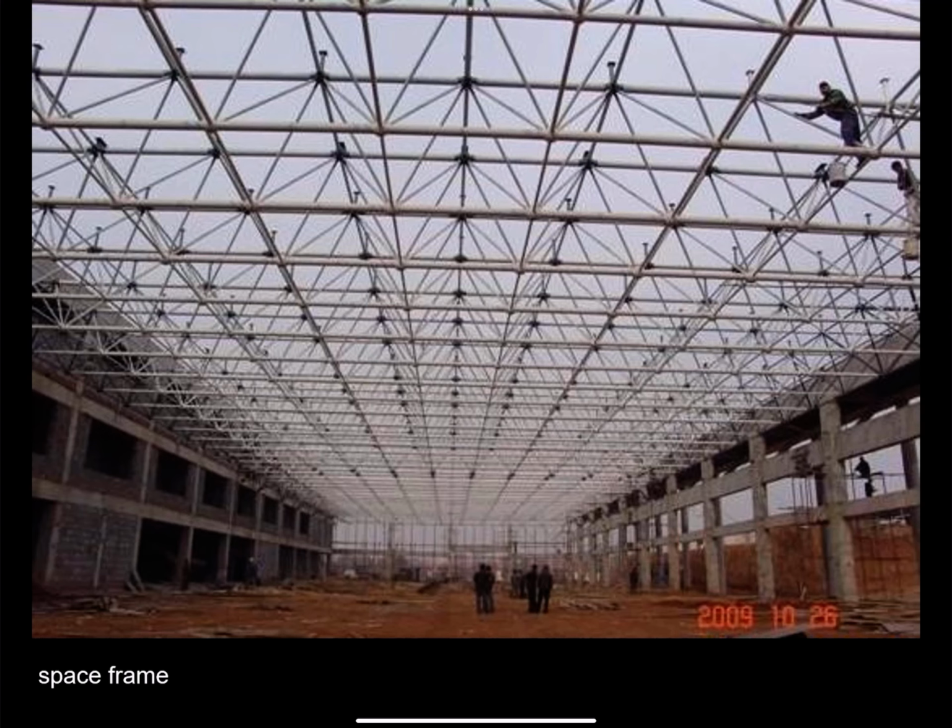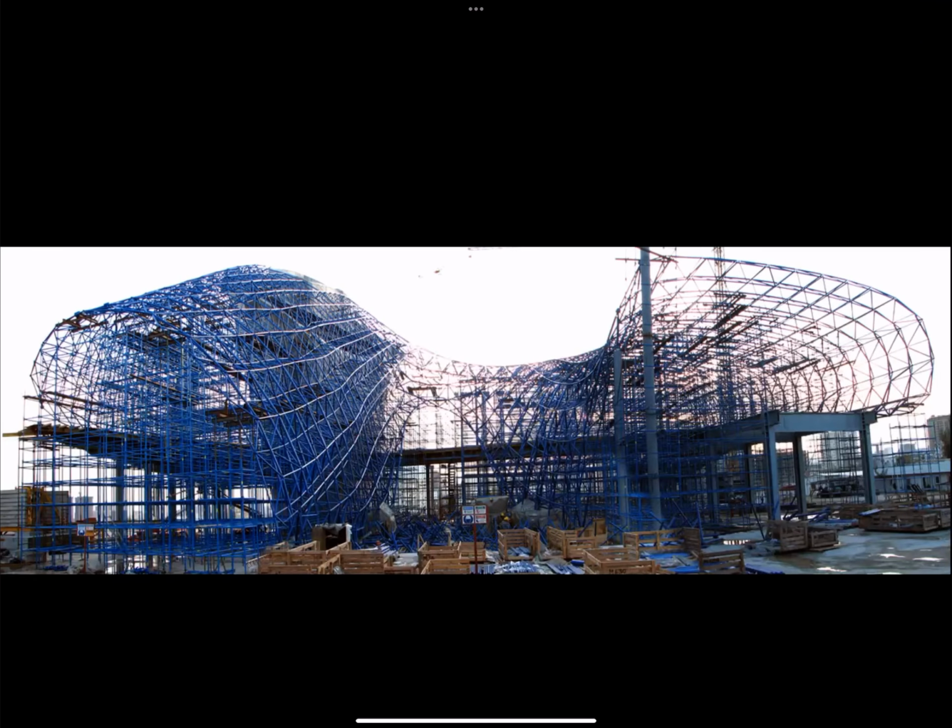And so the depth of this plane is probably about 8 feet. You can see that the worker can stand in the depth of the structure. You can see that the structural elements are very slender. And this forms an extremely stiff structure that can span up to 150 feet. And so this is called a space frame, the continuously triangulated surface. So this is it in its simple planar form. This is also a space frame.